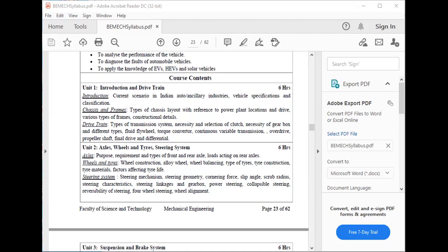The hub is connected to the input shaft of the transmission with a spline. Friction linings are separated by the springs. The springs allow the lining to slip while engaging and disengaging. Friction linings are connected to the central hub by torsional damping springs, which help to dampen the shock and isolate the engine vibrations. This is the friction disc.